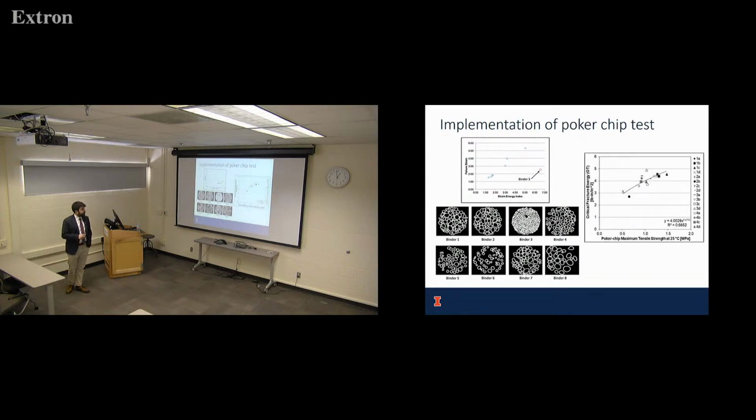We also showed a pretty nice correlation with the Texas overlay test. Okay, you might say, oh, wait a minute, 0.67, that's not amazing. But you have to consider, this is the critical fracture energy from the new overlay test spec, which is much better than the old one. And these are 16 different mixture types. In these mixture types, we had different amounts of RAP, different additives. Some were polymer modified binders, some were not. Different aggregate gradations and different aggregate sources. So all of those confounding variables, and we still saw some link.